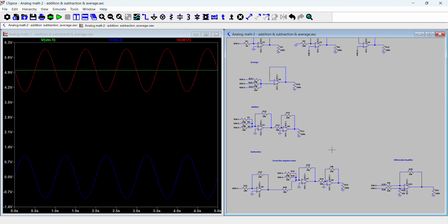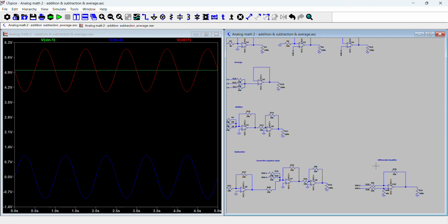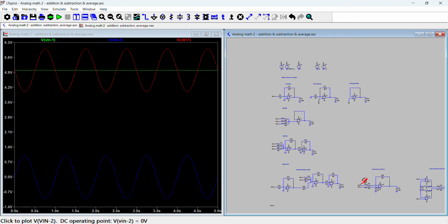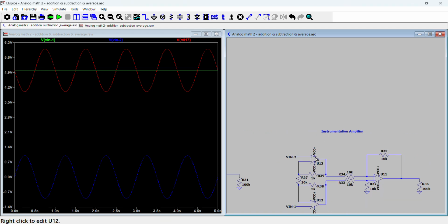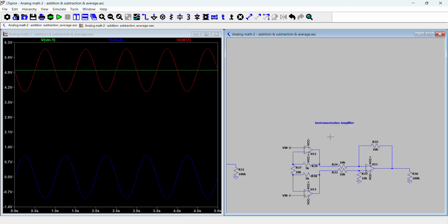Lastly, I want to talk about a circuit that does exactly that, basically buffering the inputs. And this is the instrumentation amplifier. It's called an instrumentation amplifier because within sensitive instruments, let's say a temperature sensor or a passive motion sensor or something like that, the voltages generated cannot drive a really large current because the energy input into the sensor is very small, right?